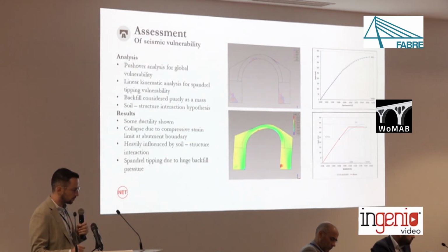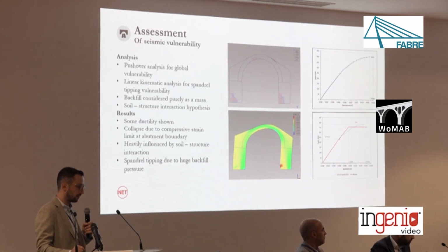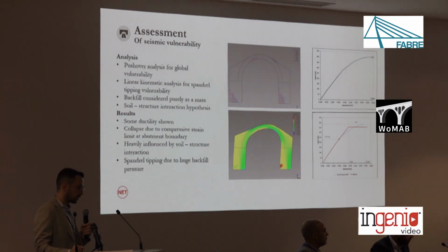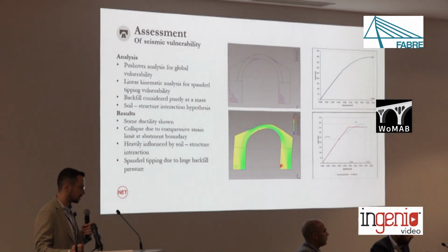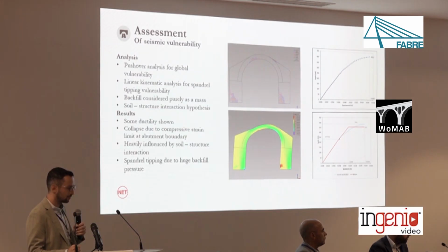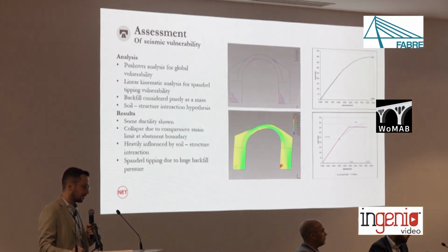Having not studied the backfill, no mechanical characterization, the backfill was considered purely as mass, and this for sure is a very safe assumption, but was the only one maybe available at the moment. And a word has to be said about the soil-structure interaction, which maybe yesterday we've seen some glimpses. But I consider maybe the biggest topic to discover, and hopefully the next workshop will go throughout the whole thing.